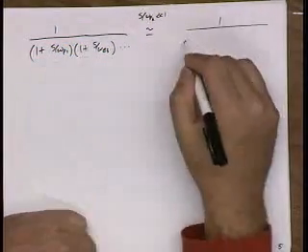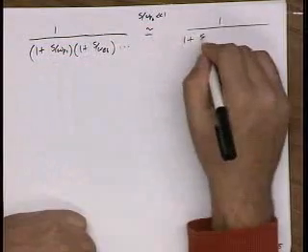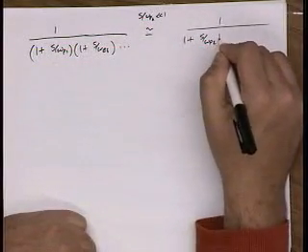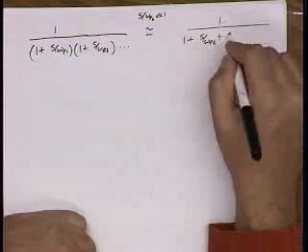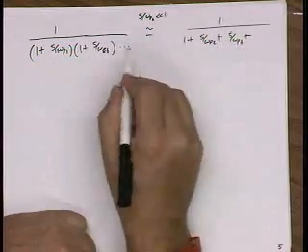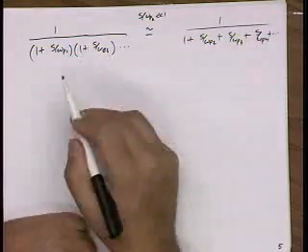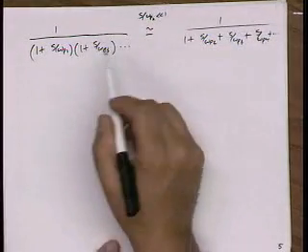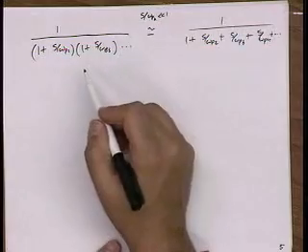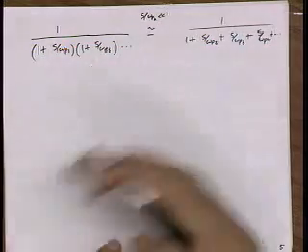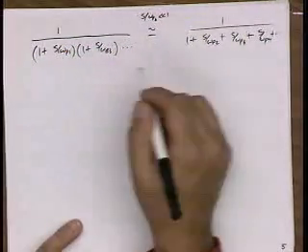So if I multiply these out, I get 1 over S over omega p2 plus S over omega p3 plus S over omega p4. And all the other terms are going to be much smaller, right? Because I have S squared terms, they're even smaller, S cubed terms. They're all too small to worry about, okay?